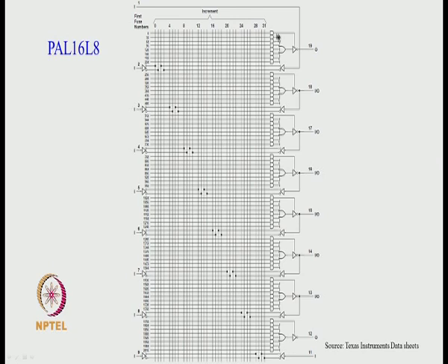That means if this AND gate output is high, the output is available; if it is low, it is tri-stated. So this is a dedicated output which can be enabled or cut off. Similarly, that's pin 19, and pin 12 is also a dedicated output. So there are 1, 2, 3, 4, 5, 6, 7, 8 outputs, as shown here.